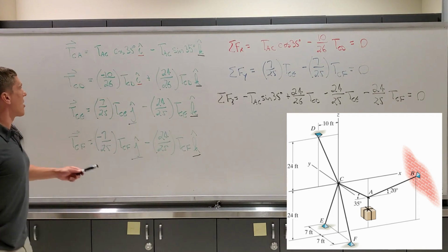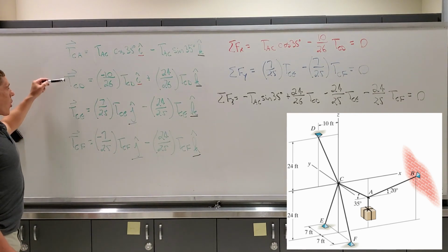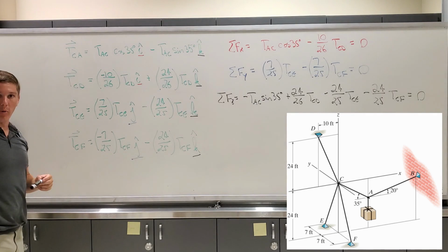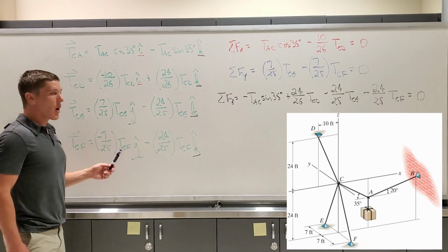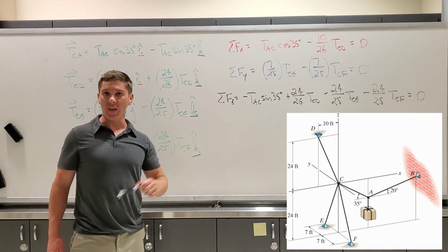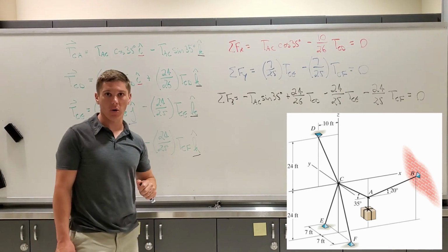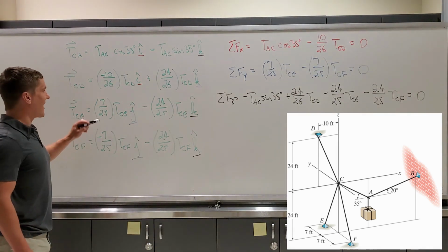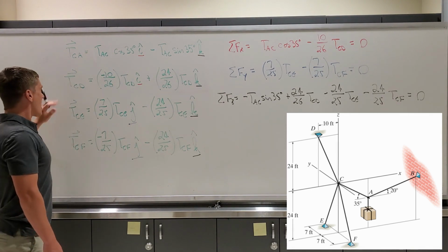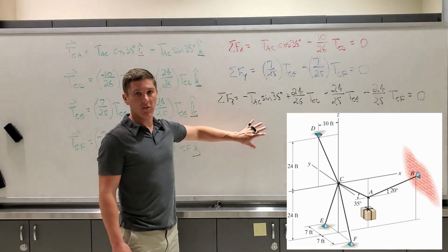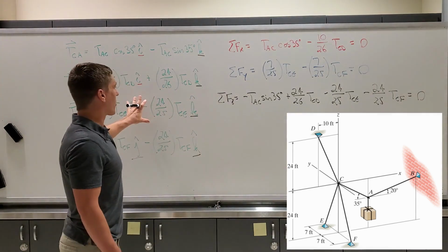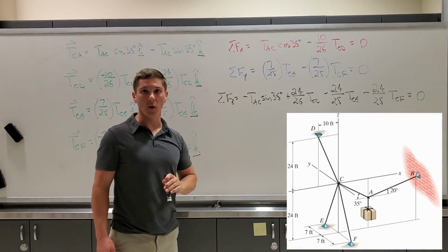In this case, it's pretty obvious because we ended up having 4 different forces acting on our particle equilibrium, but it's really common for problems to work in 3D in which you'll be looking at a particle and you may only have 3 forces acting on that particle, and students always forget to go from your force vectors. You have to then convert them into your equilibrium equations. Do not forget to convert your force vectors into your equilibrium equations.